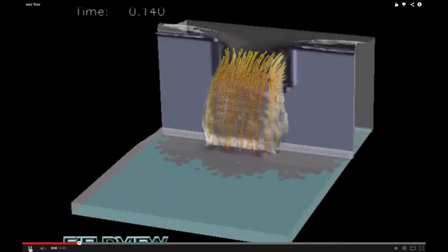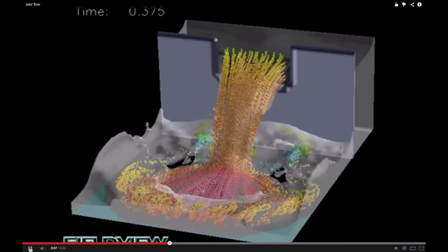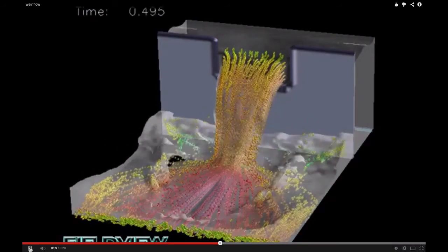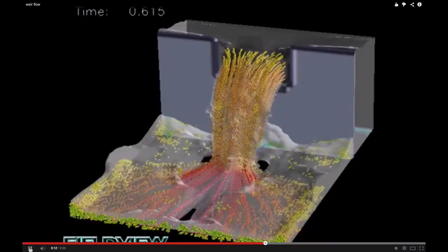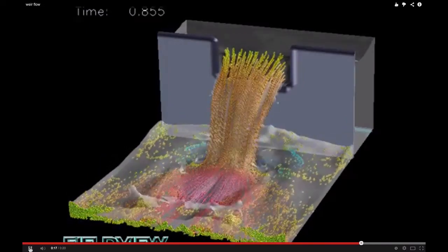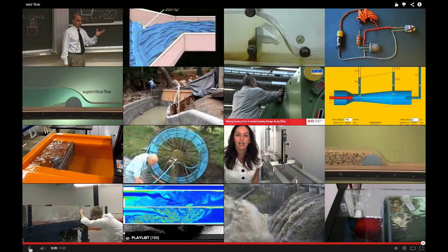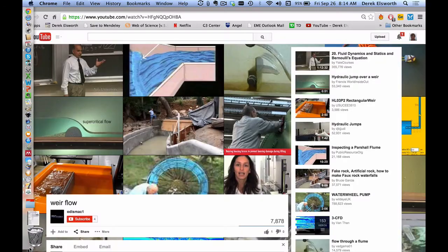So this is the idea. I mean, these vary from taking a low head dam that goes across the Ohio River, where you can measure the stage, the height of the water above that, to be able to say what the flow rate is down the river, to taking into the field a piece of plywood that has either a rectangular notch cut in it or a V notch, putting it across a stream, measuring the height of water in that notch above the bottom of the notch, and using that directly to be able to calibrate for the flow that's in that stream when it's unimpeded. And so those are the methods that we'll talk about today.